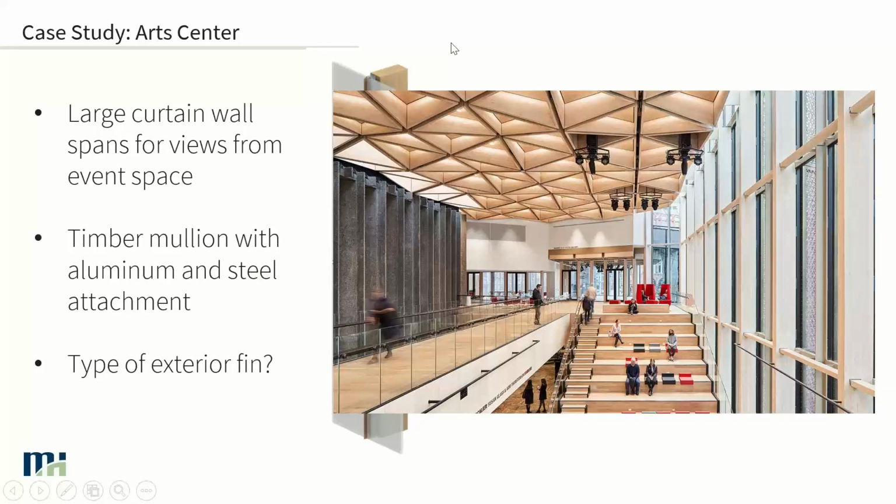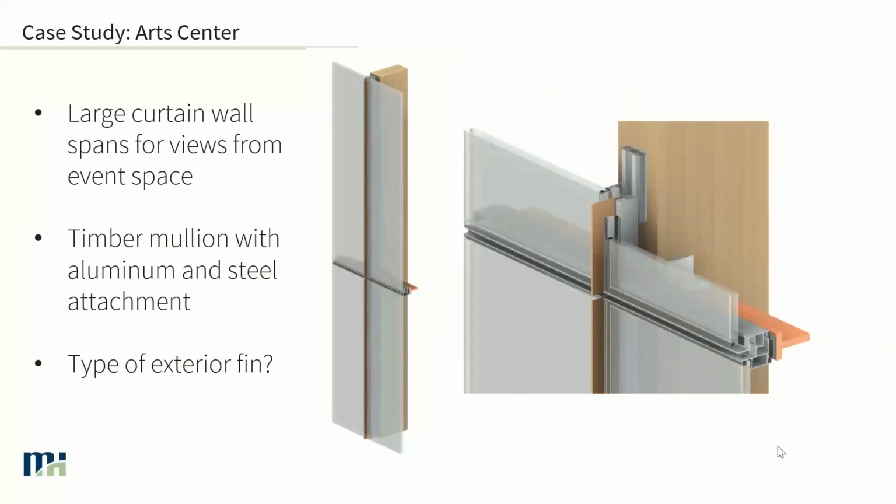You've got your timber mullion at the back. Here, you've got your attachment system to that timber mullion, but then you've got this aluminum kind of half frame to hold the IGU into place. And then you have these fins that stick through the system and essentially pull back through in past the IGU, which is your thermal layer.